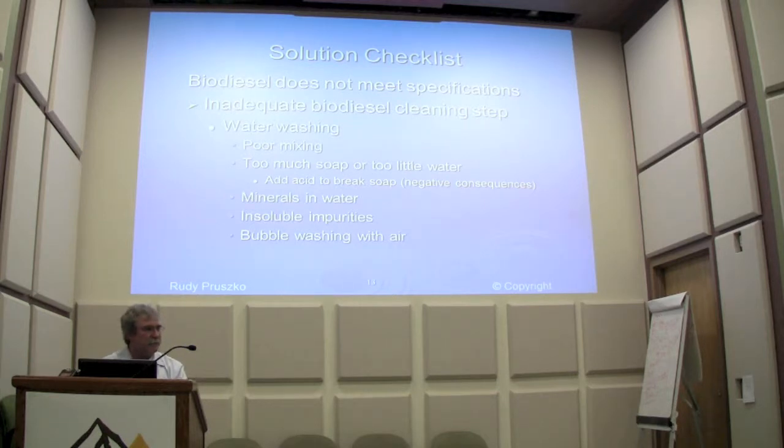Aren't, on the large scale, most people adding acid to neutralize the reaction anyway? Which may, if you got any soap, going to do the same thing. Yeah, that's where you have to be very cognizant of how much soap you have, or how much FFA you started with, how much soap you created.